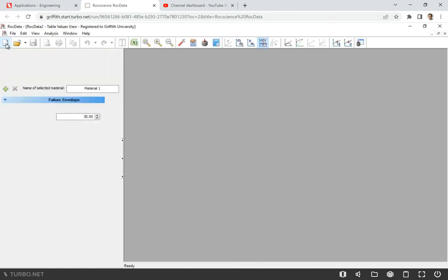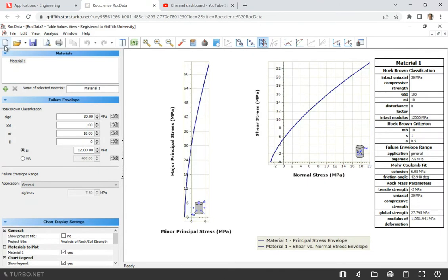The slope will be blasted, so we can describe it as good blasting, and then it will be mechanically excavated. So what we need to do is estimate the strength characteristics of this rock mass. We're not given any data from laboratory tests, so we'll have to use the reference data. The way we're going to do it, we just start a new file here. And we already have this reference data here, the one that we can use.